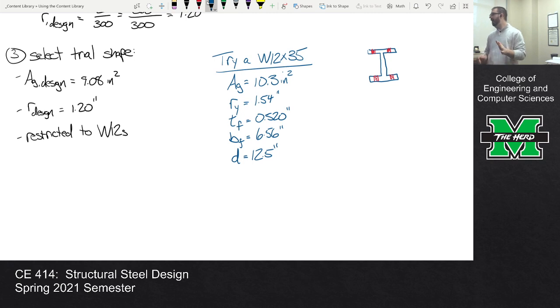No problem. Now, keep in mind, this is a W section connected via the flanges. So we are going to need to take this section, split it into an equivalent WT, and look up that X bar connection, which is going to be Y bar. I think we've done that enough by now that we know that X bar connection for a WT connected via the flanges is the Y bar for the equivalent WT.